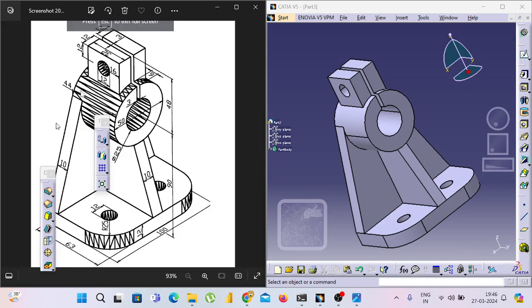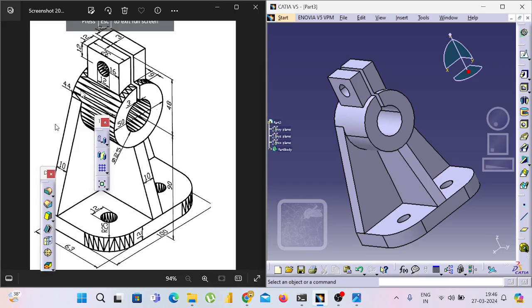As it is according to the exact dimensions, I had drawn this figure. Again I am saying that first we drew the base plate, then we drew the circle, then we drew the back side of the plate, then we used the stiffener. Then I created one plane definition and mentioned the distance, then I drew the rectangle box, then I did the pad, then I drew the hole, then I split the square into 2 parts. Right, like this we can draw simple figures. I have one more figure, I need to share that one.